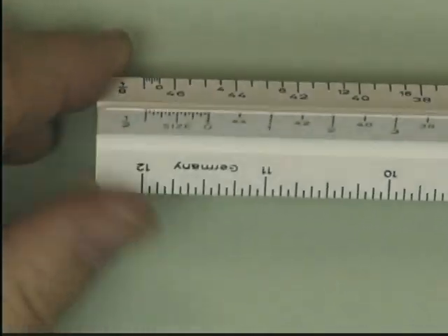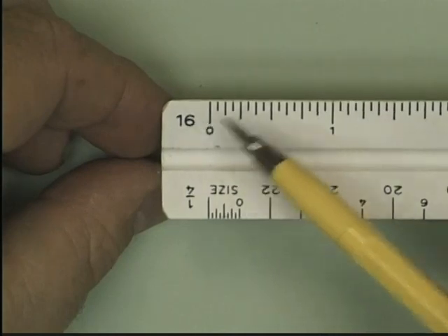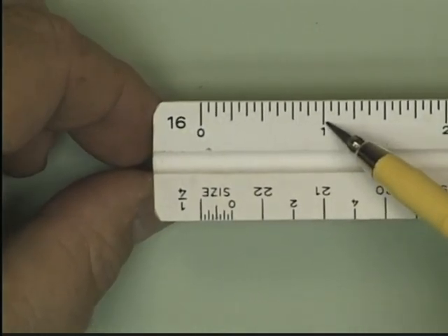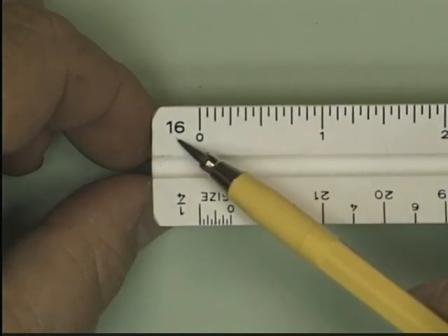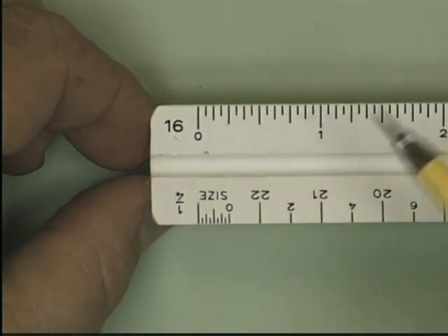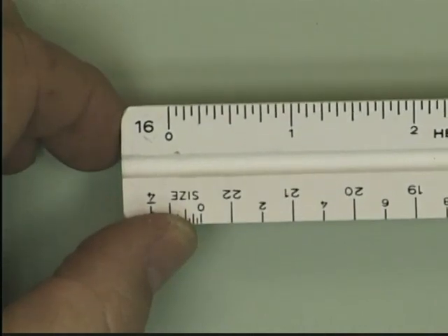Again, most of the time, you will find that the key to reading the scale is to see how many divisions. First of all, see what the major divisions are, see whether they're inches or meters or fractions of meters, and then to look at this number to see how many divisions they've divided that unit into, 16 or 50. These scales, again, if you invest in a good one, can last a lifetime.